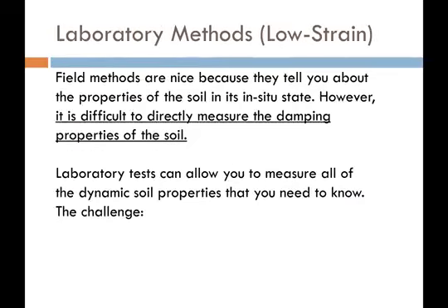Now, field methods are nice because they tell you a little bit about the properties of the soil in its in-situ state. And I love field methods. They're usually cheaper, and I trust the results a lot more because we're leaving the soil in its state as it is in the ground. But it is pretty difficult to measure the damping properties of the soil.